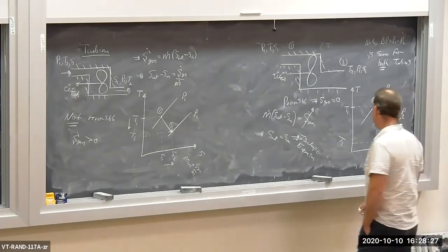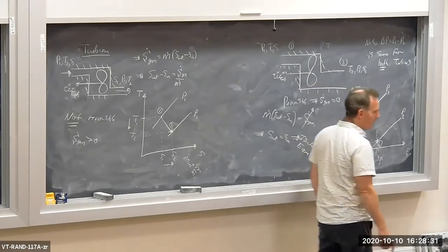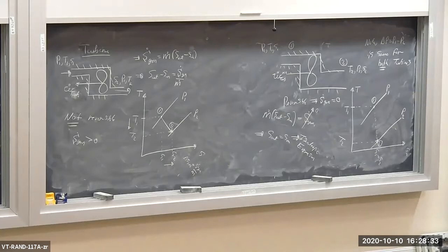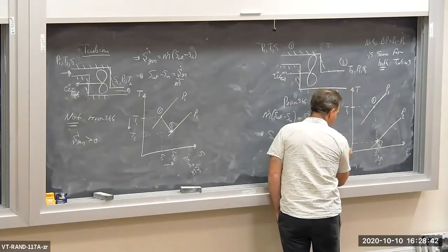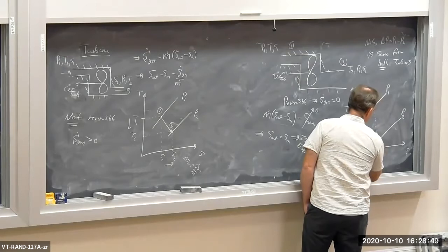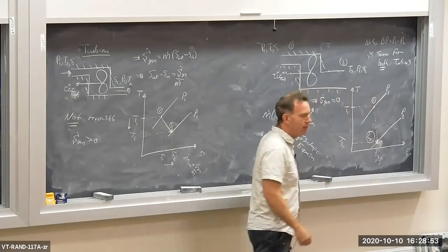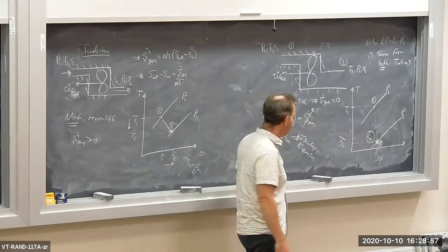By the way, this state 2 is kind of a special state. It's the state for an isentropic expansion. So I'm going to put a little S right after the subscript 2, and I'm going to call this state 2 sub S. I'm going to put a circle around it. 2 sub S means for the constant entropy process.